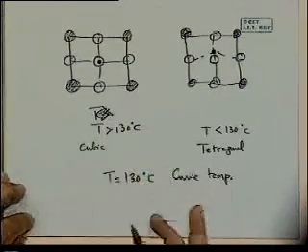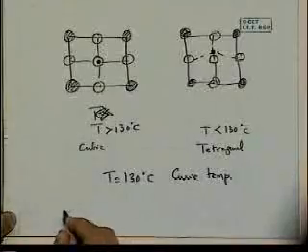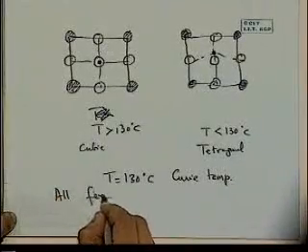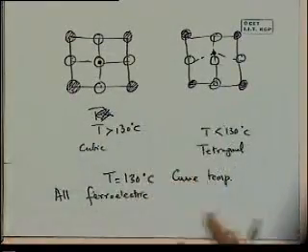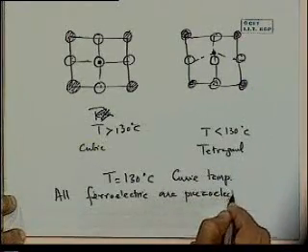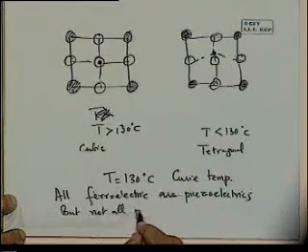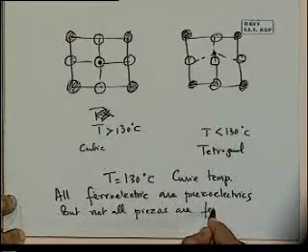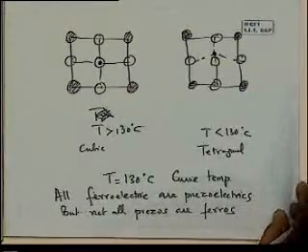Okay, and this is basically the ferroelectric. There's a net dipole moment, a permanent one. The name comes from similarity to ferromagnetism. We've got permanent dipoles. And one comment I'll make here: all ferroelectrics are piezoelectrics. We can guess that because if there's a net dipole moment, if I shift it, I'll get changes there. Okay, so all ferroelectrics are piezoelectrics, but not all piezoelectrics are ferroelectrics. I'm just abbreviating piezos and ferros, but you can expand that. Okay, so this is basically ferro. There's a permanent dipole moment.